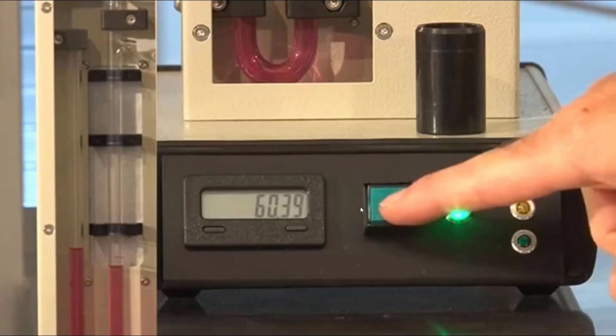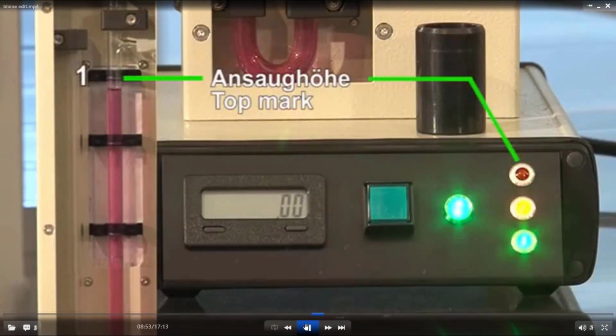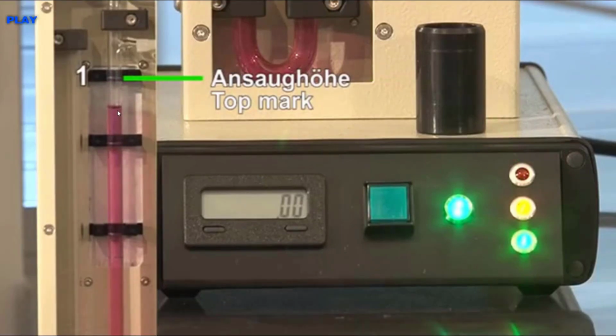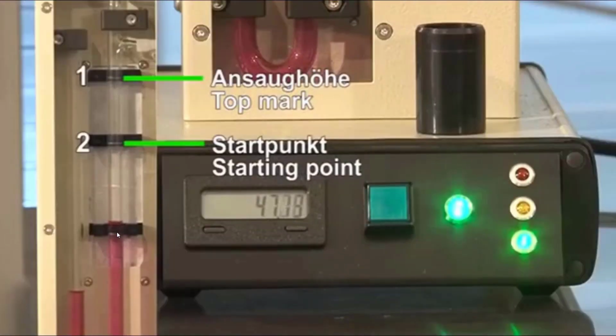onto the top of your device, you will just press the button so that it automatically sucks the manometric fluid, and the timer would start between these 2 points automatically. You are seeing that the manometric fluid is dropping with some constant rate, and this is basically a start point. The machine is automatically started. After reaching the finish point, it will be automatically stopped, giving you a time between these 2 points.